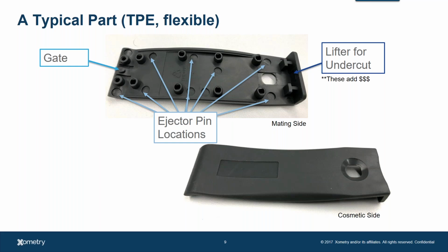And something you'll see on the gate here is the gate is a little bit protruded because once it's molded, that piece is clipped off, usually with a diagonal cutter manually, and then put into a bag or wherever you're organizing your parts. Sometimes when you're using a harder plastic, you can find the gate location on that part by looking for something that looks like a roughly sanded piece.